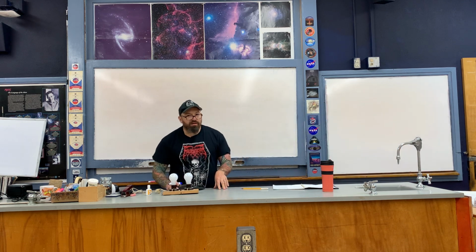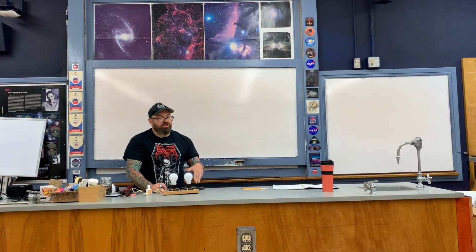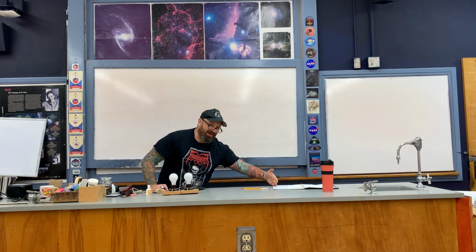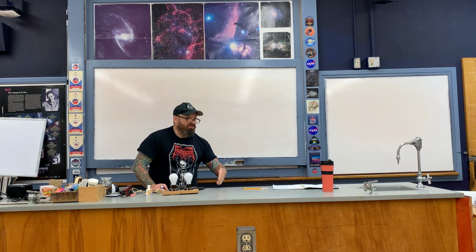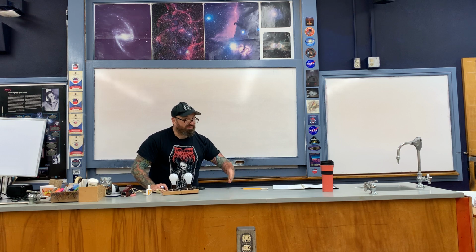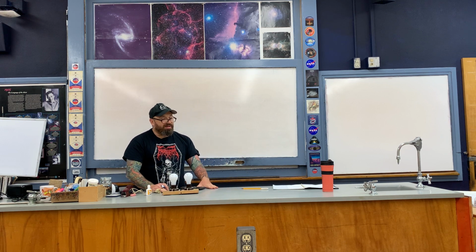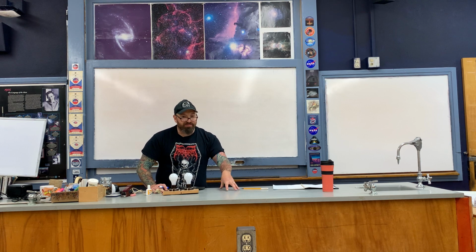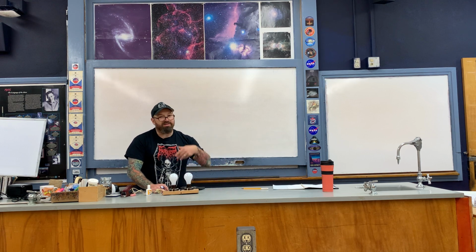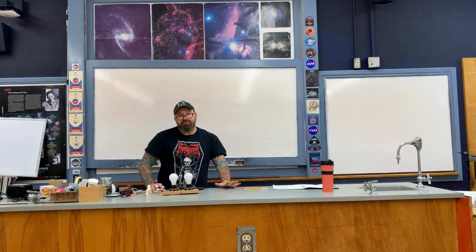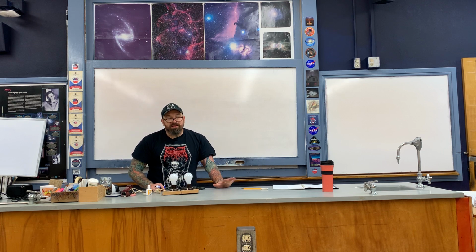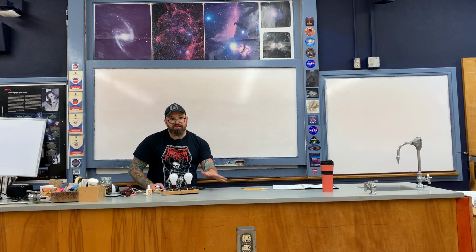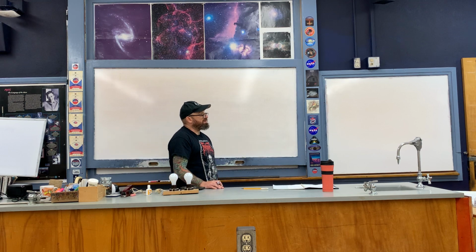Okay, so this is going to be a parallel circuit problem where you're basically going to be turning on more and more things in your house. Okay, when you do this, when you lower the resistance by turning more and more things on in your house in parallel, this then means that ultimately more current is flowing through your house. If the current reaches a high enough value, then that current could start to melt the electrical wiring. And then if that happens, it can cause a fire, etc., etc. So to prevent all of that from happening, what is built in series with respect to everything else that is in parallel is what is called a fuse. So let me describe that here in the context of this example.